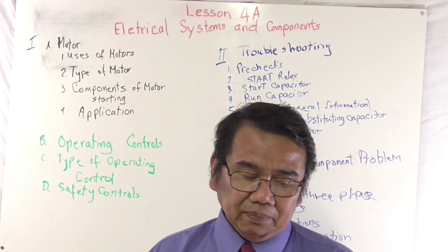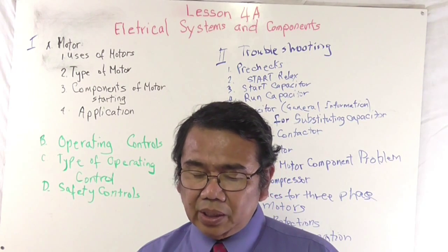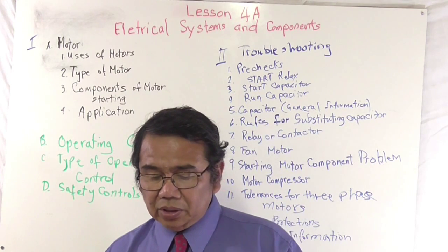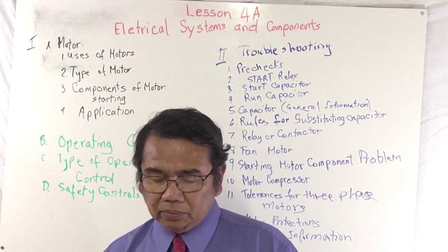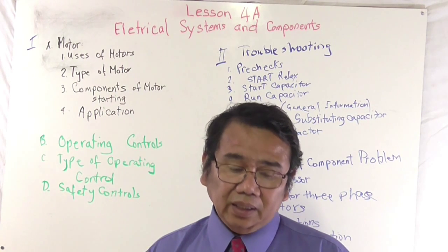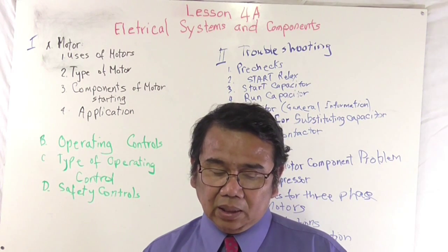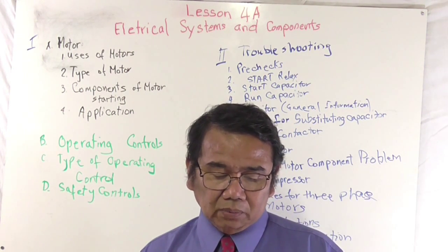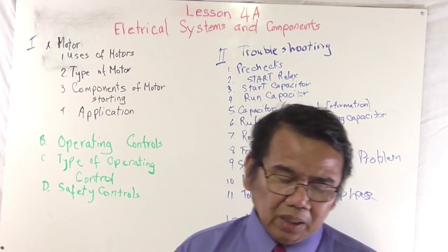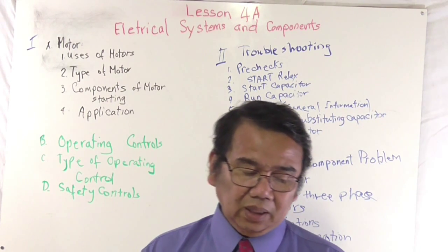By metal type: you get a 2-terminal type mounted on the shell or dome of the compressor, in series with the compressor common, reacts to excessive current and heat, and can be referred to as a 2-terminal click-on.